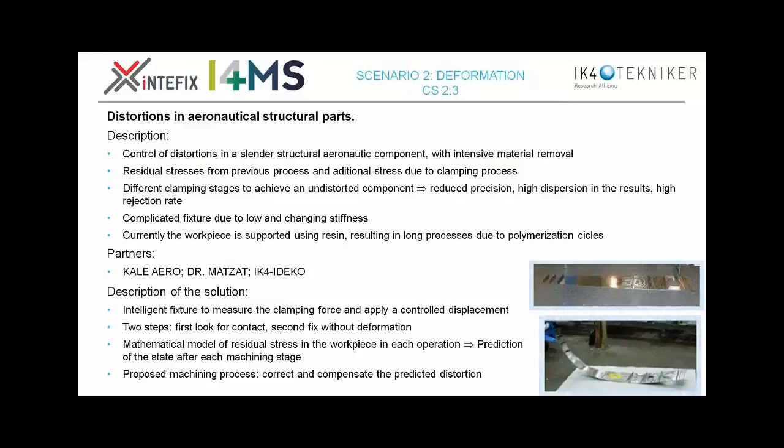So we avoid the introduction of additional stresses due to deformations associated with the clamping, and also through a mathematical model of the residual stresses and the deformations occurring in the workpiece for different machining steps.